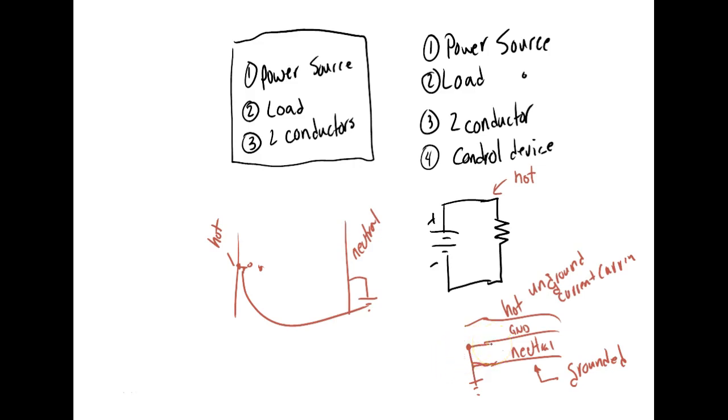And like I said, unfortunately in PLCs you do not put dots at connection points. How many loads per line? One load per line. I should say that's the maximum, but I should also say the minimum, right? Well, that's not true. One load per rung. So every rung has to have a minimum of how many loads? One. How many loads per line? One, maximum of one. How many loads per rung? Many.